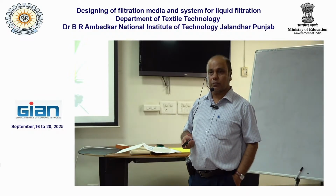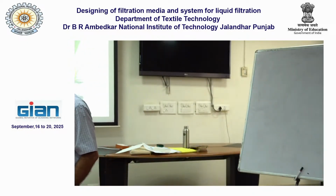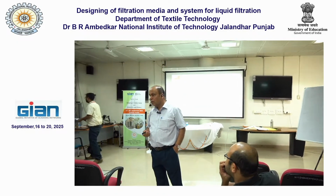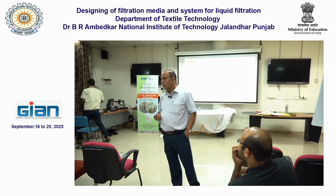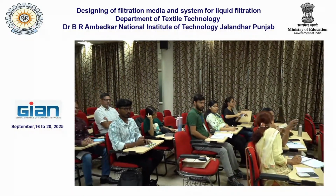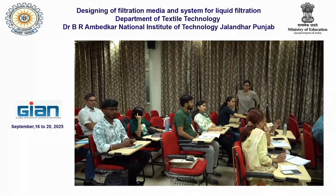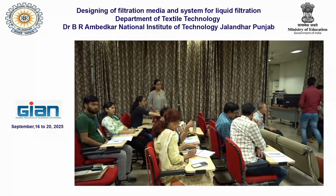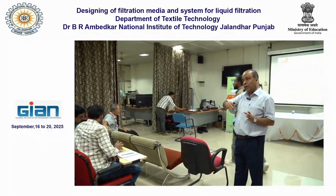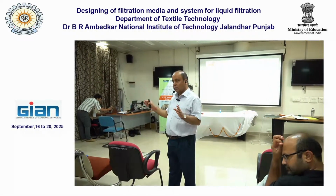Industrial RO and backwashing, and how things are performing. In an industrial RO system, backwashing or cleaning is done regularly. Now, industrial wastewater treatment, as I told, is a multiple-stage process. Initially, by coagulation and flocculation techniques, you can remove all sorts of heavier, large particles. Then you can go through the filter press to remove the cakes.